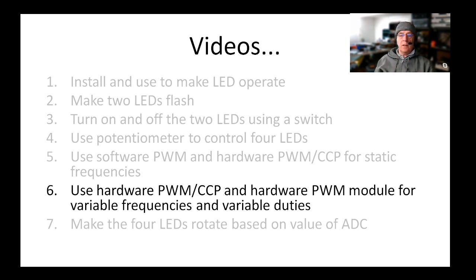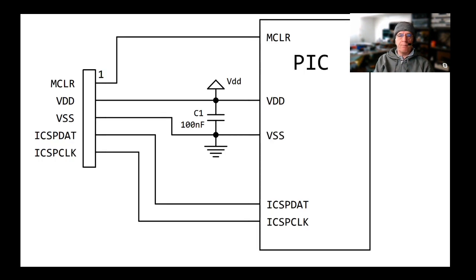And then we're going to use, in the same microcontroller, a hardware module called PWM. And you might need to do that because you might want to use the CCP compare module for another task. So they've given you a dedicated pulse width modulation. And to be quite frank, the CCP version of the pulse width modulation module is very old. It's been there for a long time, and generally most microcontrollers have that. Tomorrow we'll be going back to LEDs and we'll do some rotation stuff and just widen the language skill set.